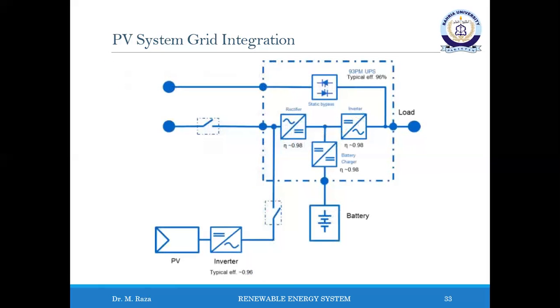Grid-connected photovoltaic systems are composed of PV arrays connected to the grid through a power conditioning unit and are designed to operate in parallel with the electrical utilities. The power conditioning unit may include the MPPT, the inverter, the grid interface, as well as the control system needed for sufficient system performance.